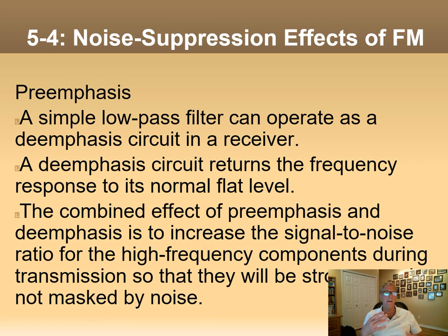So there was a non-linear characteristic to the mechanics that were going on with the needle. What they did is they added basically a pre-emphasis, and it's not linear like this. It's called the RIAA equalization curve, Recording Industry Association of America, and you can look it up.